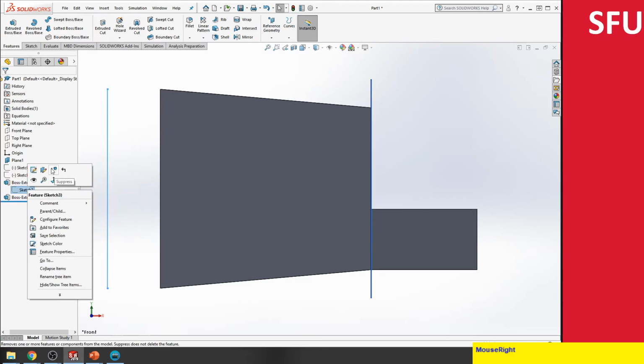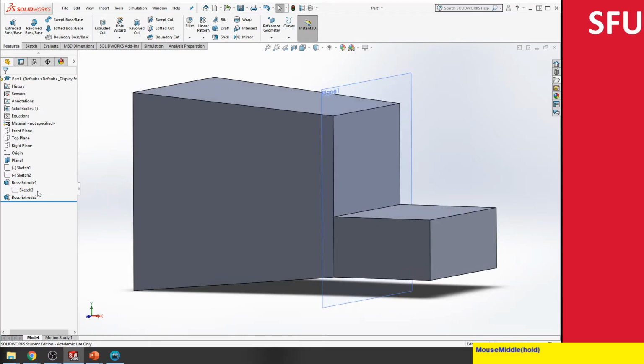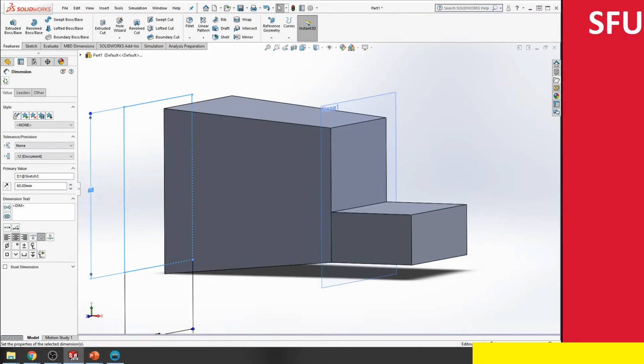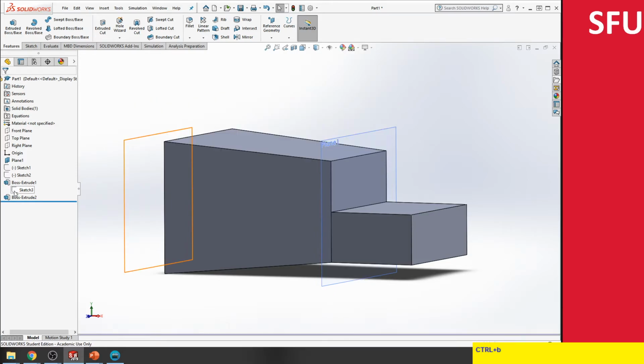So I can't actually edit this particular shape from this view. You can select this and then maybe make this a little bit smaller. Instead of this, if I made this say 60, my sketch would automatically get updated, and then all the corresponding parts will also get updated. This didn't make a big difference. Right now it hasn't actually rebuilt the surface or all of the objects. So what I'm going to do is hit Control B, which is to rebuild, and now you notice it's actually changed the shape.